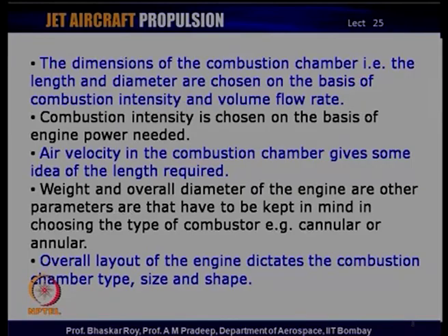So, that you have what the engine designers always call the thrust weight ratio. If you want to have a high thrust weight ratio and a low diameter to fit into the aircraft, you do not have a lot of space available for the combustion chamber, and as a result quite often many of the designers go for annular combustion chamber, which is the easier geometry to adopt, really speaking.